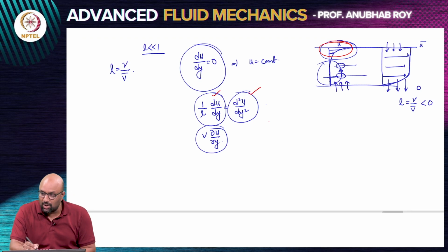You will also need to account for viscous diffusion there. And so you will have this thin layer where the velocity will transition from being nearly quiescent to u bar. Now if you see that scenario here, if you consider two levels, there is a fast moving fluid near the top plate. Because the top plate is generating the motion, there is a fast moving fluid.